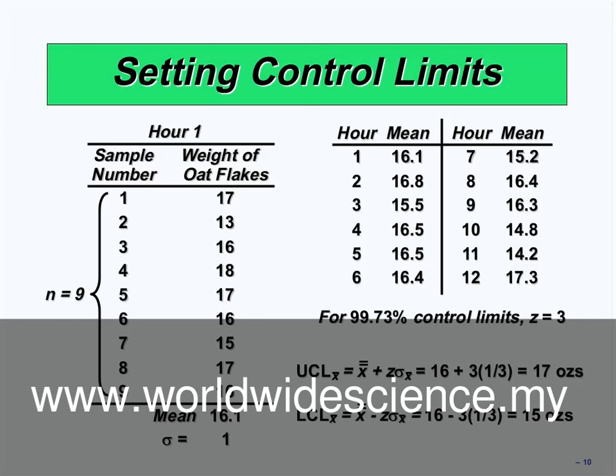Yes. The other numbers, 60.8, 60.8, 60.5, are the means of the 9 cups of the flakes in each hour. For example, 60.1 is for 10 o'clock, 60.8 is for 11 o'clock. Every hour, the operation manager should select 9 cups of the flakes, measure the weight of them, and write down the mean.